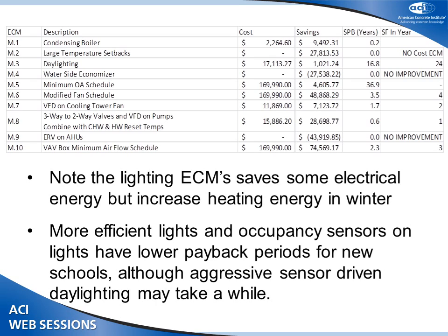All right, so going in and doing daylighting just to get energy efficiency out of that, it's going to take a little bit longer to pay that back, around 17 years, because of the additional controls that are necessary, but they do pay back, and they have other benefits. If you look at all of the studies that relate to daylighting and the performance of the students with higher levels of daylighting in there. So I just wanted to point out that energy efficiency and economics aren't the only design criteria that we have to look at here. There is also indoor environmental quality, of which quality of lighting is one aspect we have to be aware of.